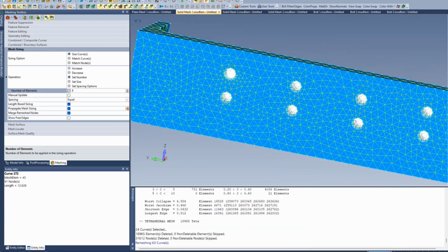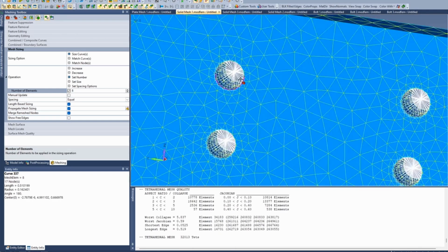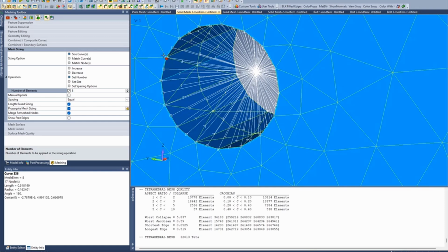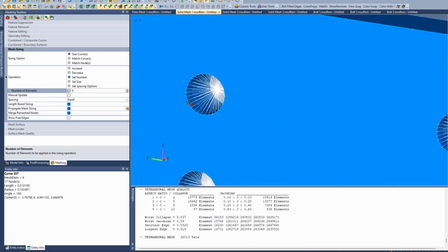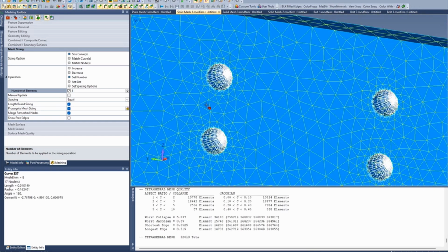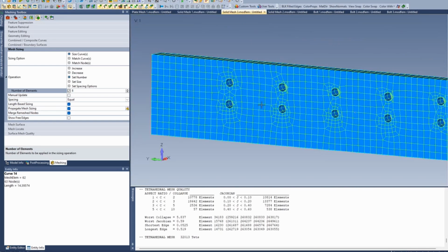We'll hit OK, and it'll create all of our changes at one time. Again, if you notice, it updates our RBE to include the mid-side nodes on the TET elements. So using the meshing tools, you can update RBEs automatically for plate meshes and a TET mesh. Okay. All right, so I'm going to turn the select off there.